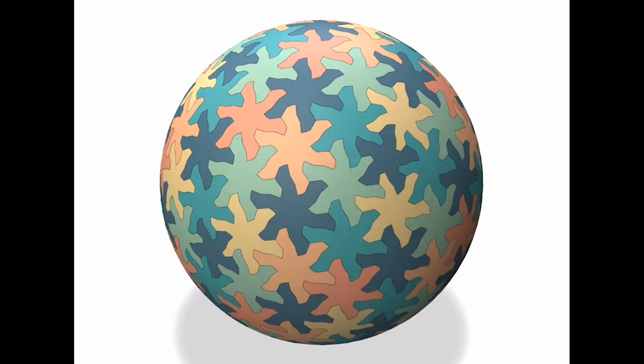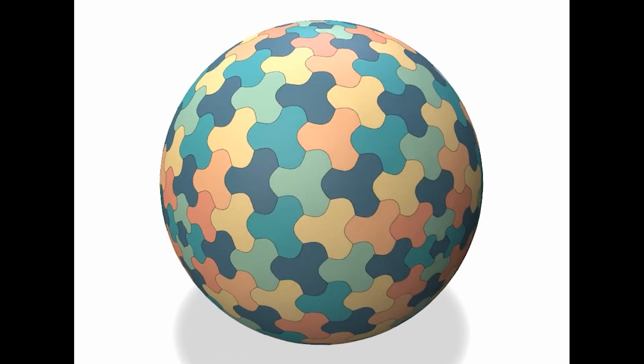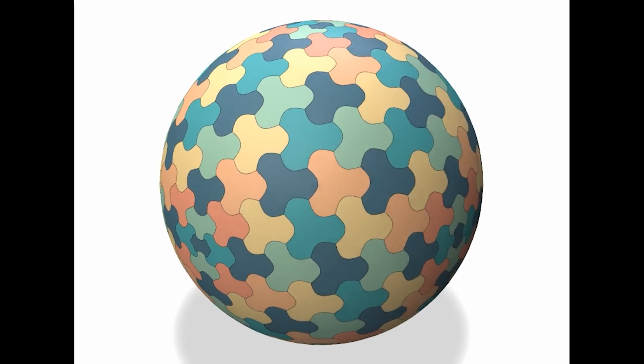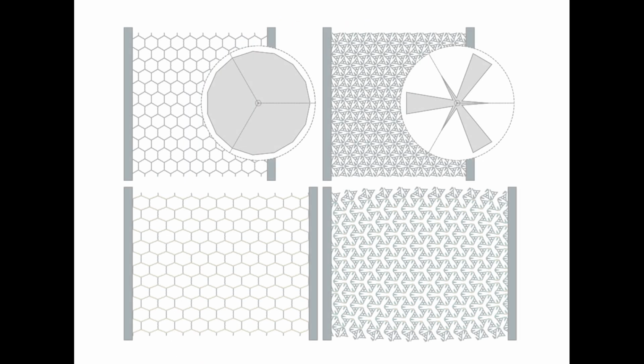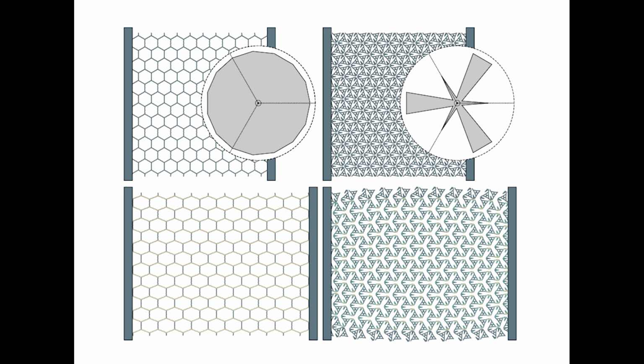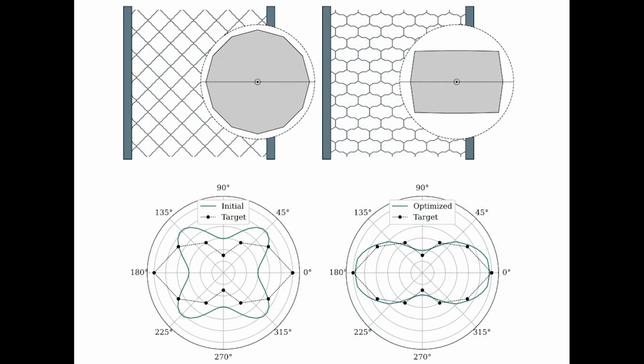This approach extends readily to higher dimensions, which we illustrate with restricted Voronoi diagrams on 3D surfaces. Our closed-form construction also enables computing derivatives of the Voronoi diagram, allowing gradient-based optimization of mechanical metamaterials.